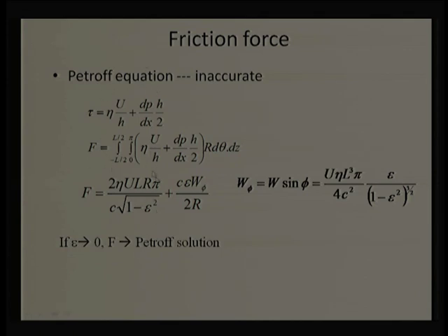But with a modification, integration of shear stress can provide good results. Of course, it is based on the short bearing approximation, so it cannot be 100% reliable, but it gives reliable results. Now, as I mentioned, there are a number of terms common in these two relations. We can take the common term, which turns out to be 2 pi eta u L r divided by c, and in brackets, the square root of 1 minus epsilon square, times 1 plus epsilon square into L square divided by 16 r square.